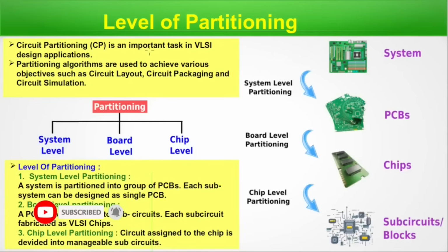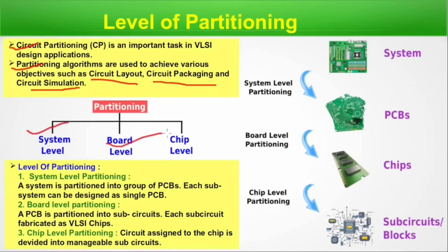Now, circuit partitioning is an important task in VLSI design applications. Partitioning algorithms are used to achieve various objectives such as circuit layout, circuit packaging, and circuit simulation. Partitioning can happen at 3 levels: system level, board level, and chip level.